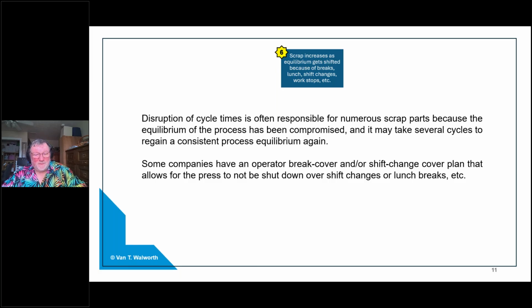And when it got disrupted and started over, that's when some more scrap can come. So once again, very similar to continuing a quote unquote normal cycle after a shutdown or after a long shift shutdown, just a disruption in the cycle can actually cause a problem. Many times, just operators I've been watching or helping, it takes a longer time to remove a part, one part sticking, then 2 parts are sticking. The press is open for 30 seconds or a minute longer than normal, and the operator just closes up the press and just continues to run the next cycle.